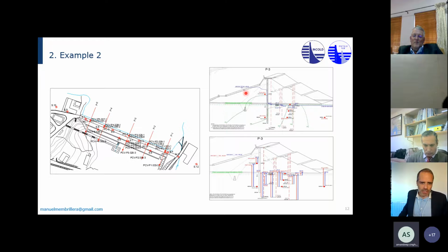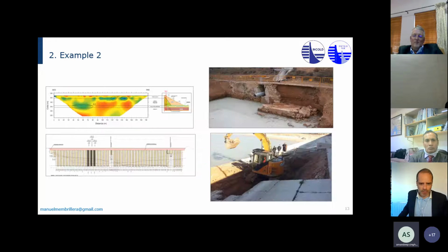And so I suggested the farmers take advantage of when the water was low, and we inspected this area. We went with a hammer, pounding on these blocks that are protecting the earth shoulder, and we found an area. So this is the upstream phase of the dam. We lowered the reservoir, and this is what we found. We found a huge hole, several cubic meters, in the upstream shoulder when we removed these concrete slabs that were protecting the upstream phase of the dam.